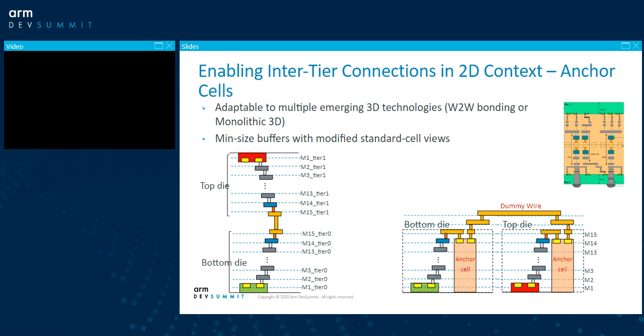So essentially, this kind of cell virtually exists to represent the two-tier 3D connection on the left here. So in our 2D representation, anchor cells are conceptually aligned in 3D and connected with dummy wires at the top layer, like in this case, metal 15, before the global supply grid is distributed at that layer. And then we cut the dummy layer essentially to snap the signal terminals to the closest assigned micro bump, also you can call it a wafer bond, and remove the virtual anchor buffer pairs, because essentially it's not required after we get the base location of this anchor cell for the cross-tier placement optimization.